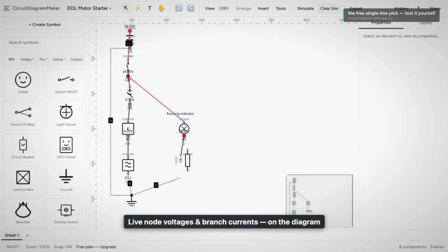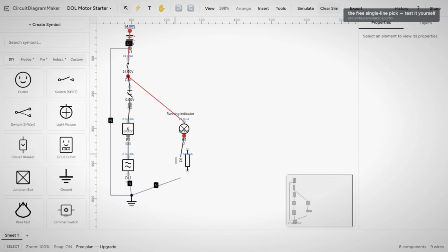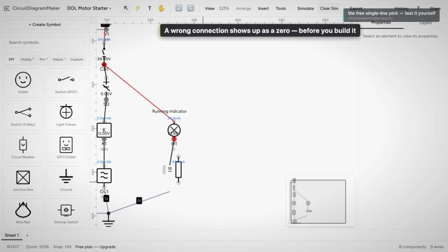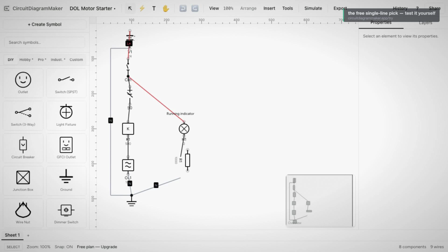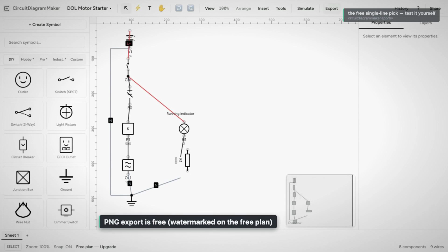Look at the connections. They route pin to pin with clean right angles, and this is the part that saves real time. Drag a component, and every wire connected to it follows. Rearrange the whole board, and the drawing stays tidy. In a picture-only tool, moving a symbol means chasing the lines and re-straightening them by hand, one at a time. Here the connections are live, so the layout is yours to reshape and the wiring just keeps up. It is the same convenience Visio's glued connectors give you, just with electrical symbols and no license to get in.